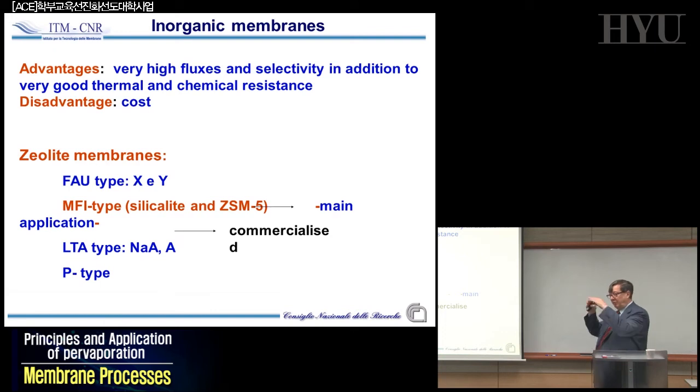You know zeolites are systems in which the selectivity is very much related to the sieving effect, because the windows, the external size of the crystals, are very, very regular. So you can have very high selectivity depending on the impossibility of penetrating the crystal, and also on desorption phenomena in the overall porosity.